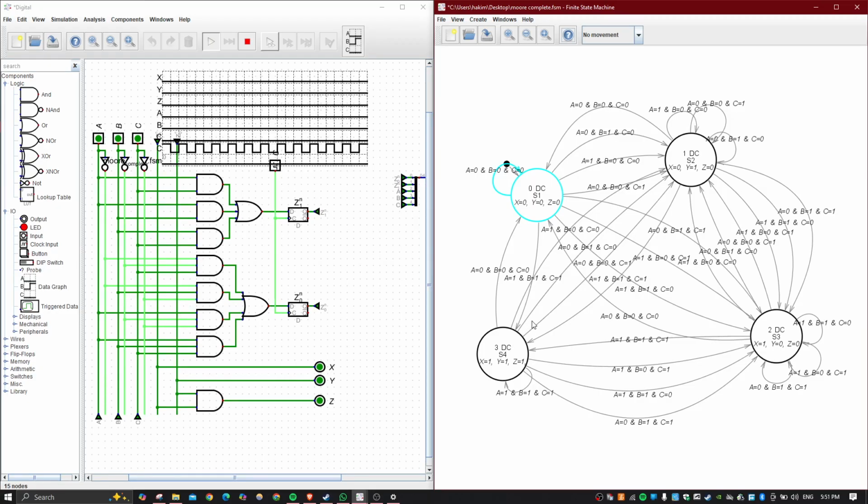Then we also need to include the input values depending on the sensor. A is the pH level, B is the turbidity level, and C is the dissolved oxygen level. When none of the sensors detects any dangerous level, it goes to state 1.